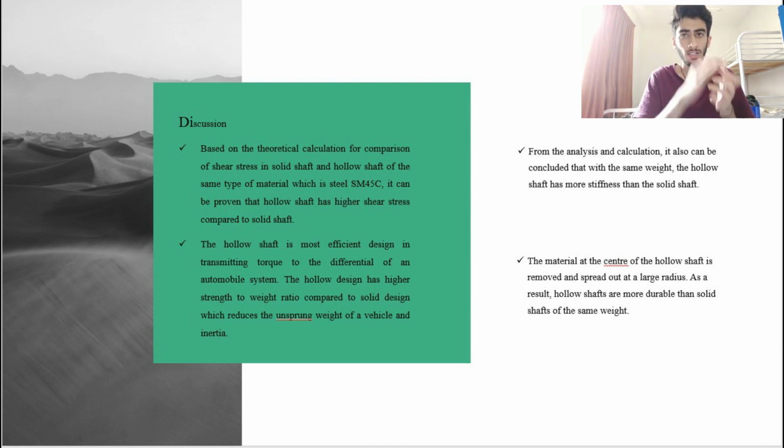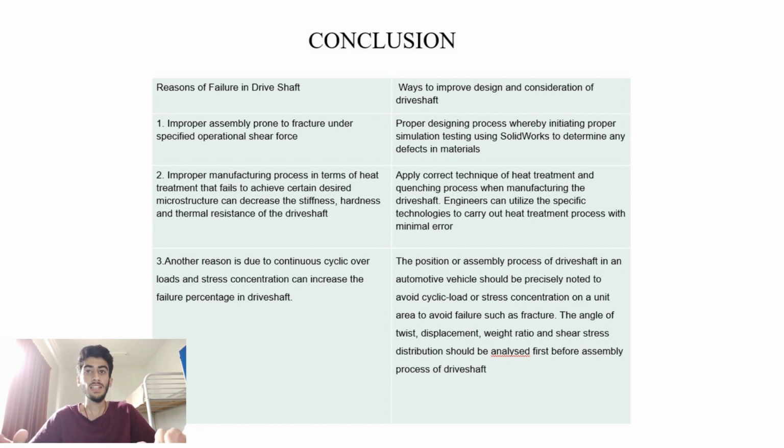From the analysis and calculation, it can also be concluded that with the same type of material and the same weight, the hollow shaft has more stiffness than the solid shaft. The material at the center of the hollow shaft is removed to spread out at a larger radius. As a result, the hollow shaft is more durable than a solid shaft of the same weight. There are a few primary reasons that lead to failure in drive shafts, so there are a few ways to overcome the failure of the drive shaft also.